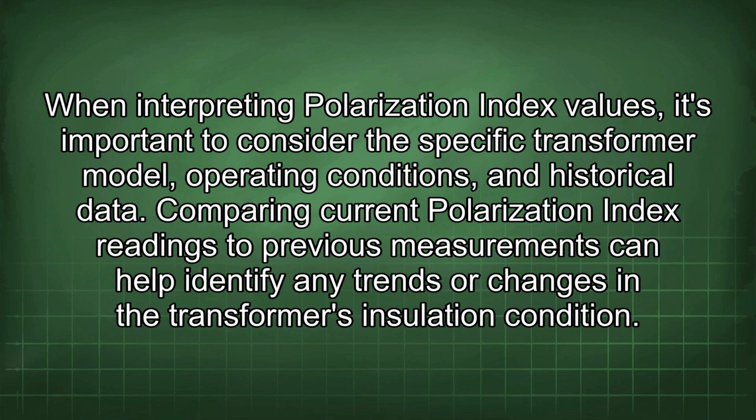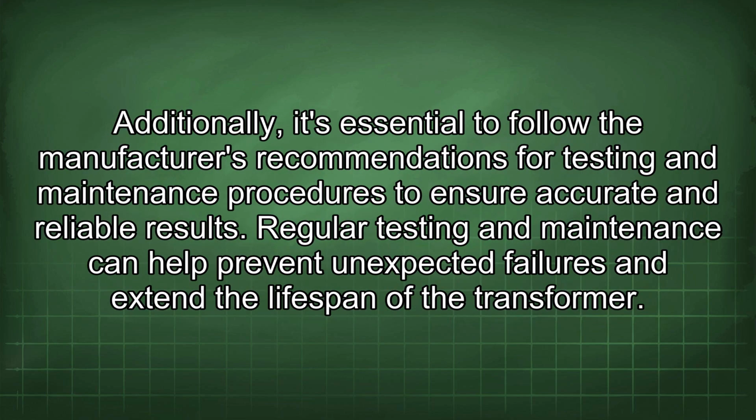When interpreting polarization index values, it's important to consider the specific transformer model, operating conditions, and historical data. Comparing current polarization index readings to previous measurements can help identify any trends or changes in the transformer's insulation condition. Additionally, it's essential to follow the manufacturer's recommendations for testing and maintenance procedures to ensure accurate and reliable results. Regular testing and maintenance can help prevent unexpected failures and extend the lifespan of the transformer.